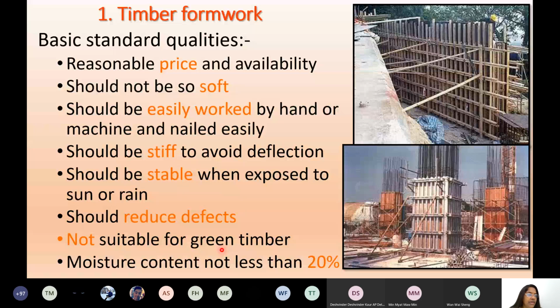It is not only moisture of the environment, it is also moisture of the concrete which is poured, right? You should not absorb everything, right? Should not be very dry in such a way that it absorbs the concrete water, right? So these are the issues related to timber. It can absorb moisture from the concrete. It can spoil, tend to lose the concrete strength. So care should be taken to avoid these problems by properly choosing the timber.